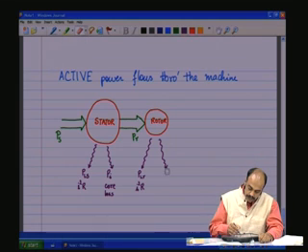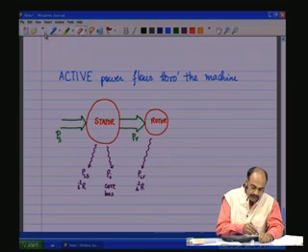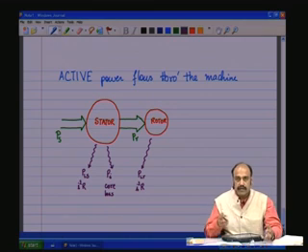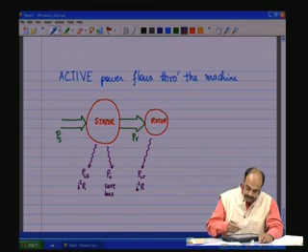So we will say that of the power input to the rotor, a portion is lost in I square R. The iron loss comprises the total magnetic core loss, including the rotor and the stator. And then further, this goes as mechanical power PM.